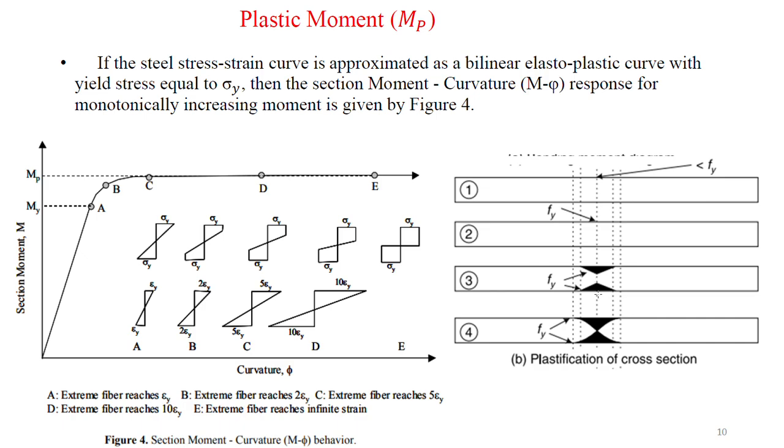Okay, at D, this is the maximum point, the maximum load which can be taken by the material. Not only D, if you keep on increasing the load, at E we can see this type of rise before going to fail. Up to the point E, it takes the constant load.